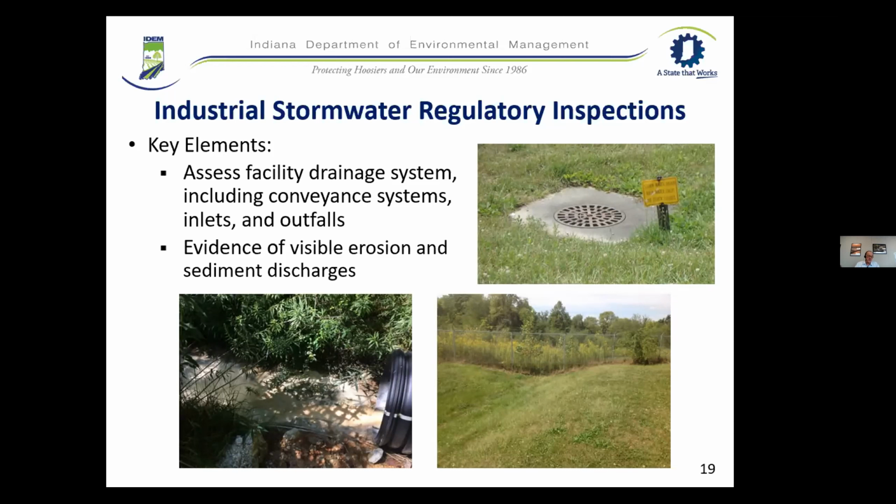We have seen situations where there's a lot of activities going on inside the building, industrial activities, where it's not going to sanitary sewer. It's going to a pipe. That storm drain inside is going outside, discharging to the outfall. When we run into that situation, that inside storm drain either needs to be connected to sanitary if it's allowable, or basically it has to be plugged, and a different approach would have to be taken to address those indoor discharges within the building.